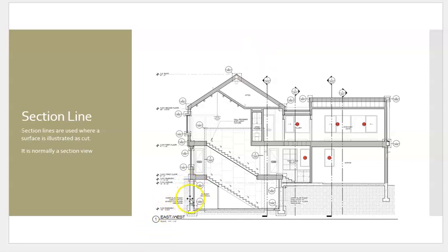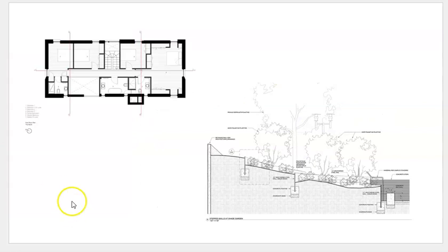Other great information on this cross section, you can see the different levels of floors, floor joists, and foundation area here in the cross section. And just so you know, cross sections will have a ton of notes around this, calling out different size materials, insulation, finishes. You got a cathedral ceiling here. Is this a truss roof, or is it stick framed with 2x12s? So we'll have all of these different details. The building inspectors are very interested in this page in particular in our working drawings because it's a lot of building code related information. This is just representation and more cross sections.